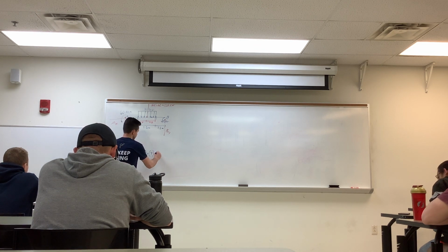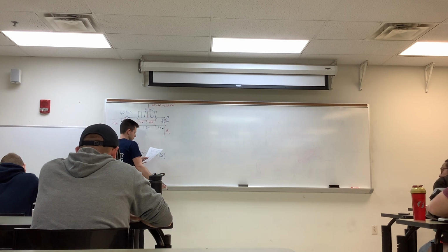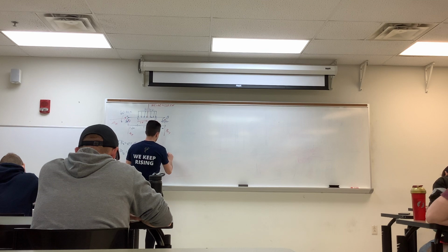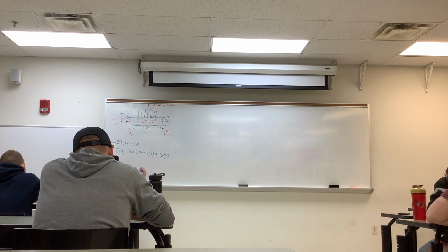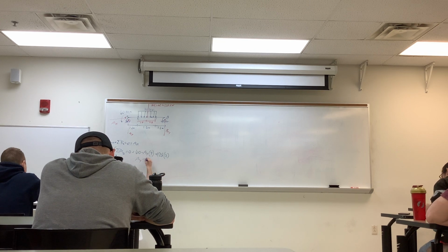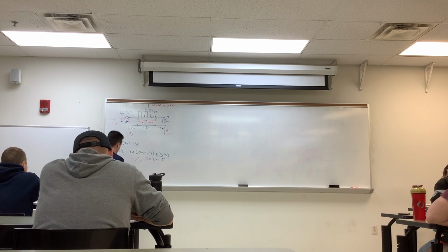And then lastly, this would have answered your question, that 128 kilonewtons multiplied by that moment arm, which is 2 meters. Doing the algebra here, we get A sub y to be equal to 79 kilonewtons, and that is positive, so it's still going up.